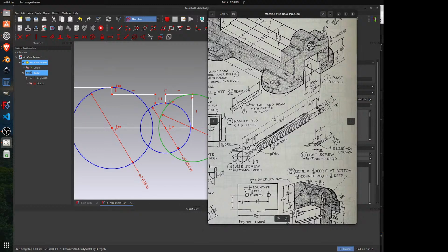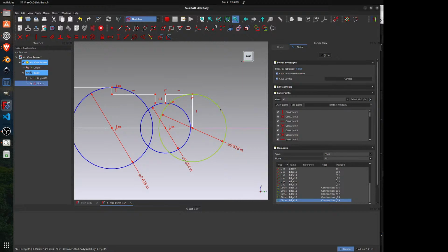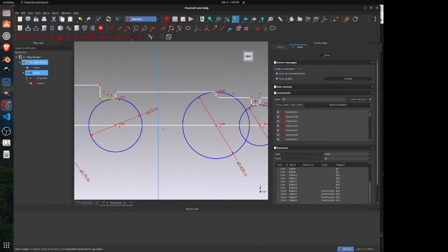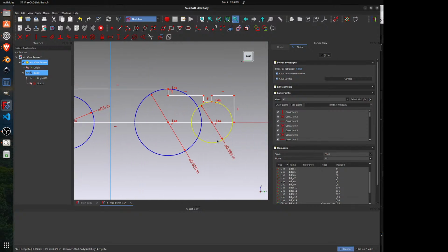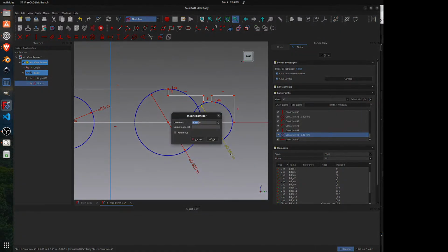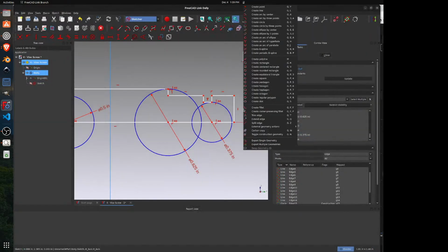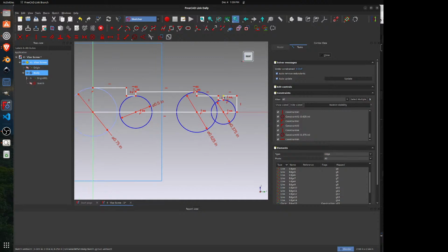All right, so it's a 1/2 inch on that end, and the groove diameter is 3/8 of an inch in here. So actually what this allows us to do, because this diameter and this groove diameter over here are the same, is I can just make these 2 points horizontal with each other, and now the diameter of this and the diameter of this will be the same. So that's a little trick there. We'll make this 0.375 inches. And so now I have all the diameters defined.